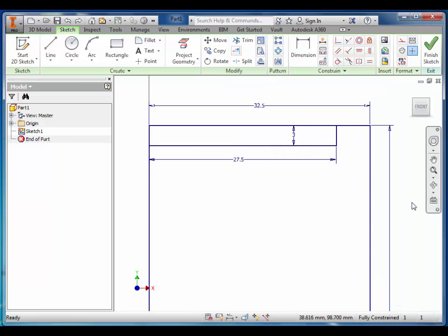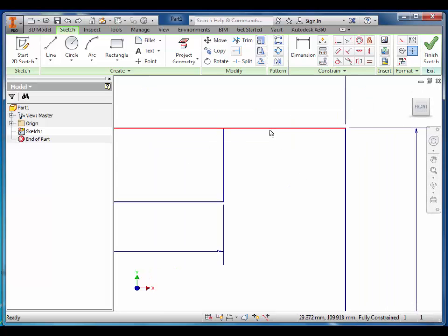The next step is particularly tricky. What you need to do is scroll into the top corner and we're going to create the lip for the can. To do that, we're going to select the arc tool. You're going to make sure that the top point of the arc snaps to the horizontal line. So click on the horizontal line, drag it down to the vertical line and snap it to that line, and create a small arc in the corner.